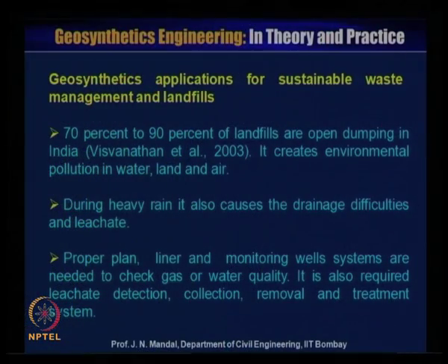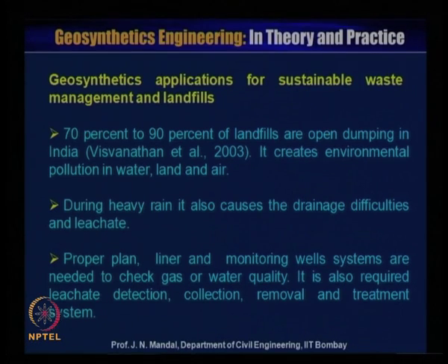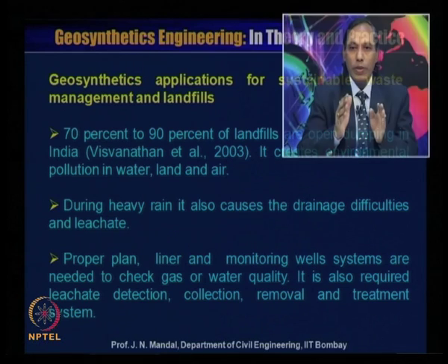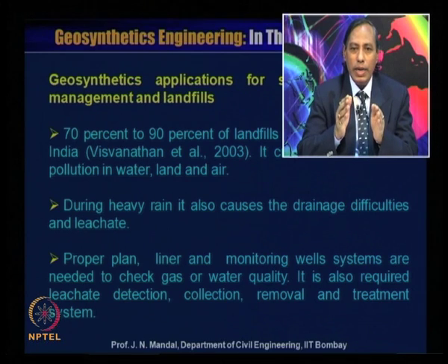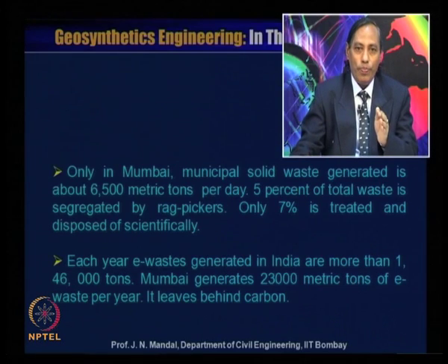70% to 90% of the landfills are open dumping in India, Viswanathan et al. 2003. It creates environmental pollution in water, land and air. During heavy rain, it also causes drainage difficulty and leachate. Proper planning, liner and monitoring systems are needed to check gas or water quality. It also requires leachate detection, collection, removal and treatment systems.